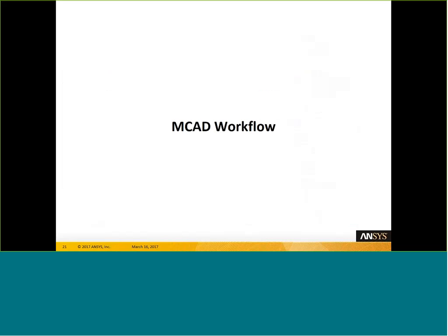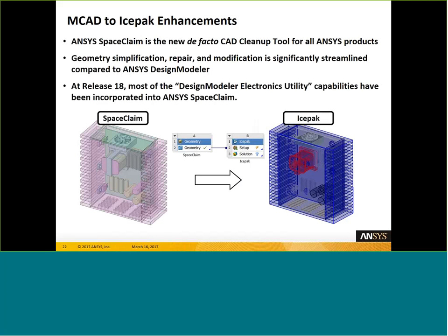And the key reason for these improvements is IcePack's linking to SpaceClaim. ANSYS SpaceClaim is the new de facto CAD cleanup tool for all ANSYS products. Geometry simplification, repair, and modification is significantly streamlined compared to ANSYS Design Modeler.